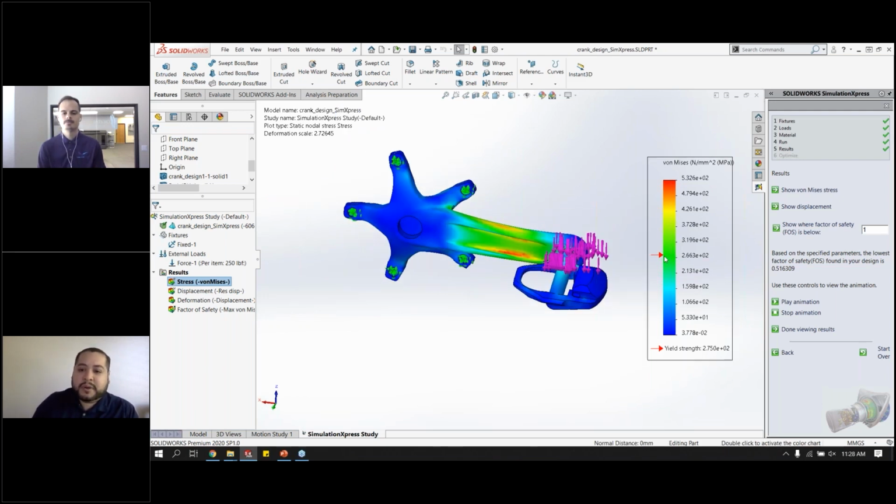And you get this marker pretty much to tell you how that max stress compares to the material limits before it starts going into plastic range, or essentially where it starts failing, right? So in this case, that max stress has well exceeded that yield point where we have a concern, right?